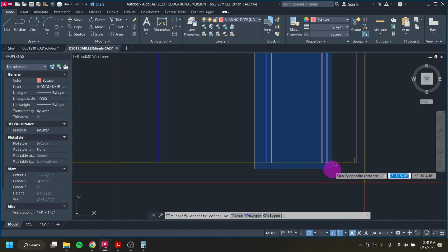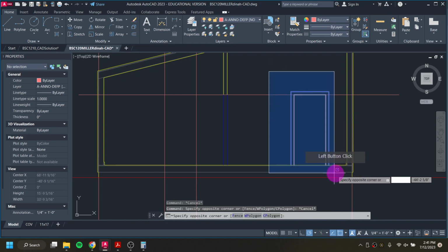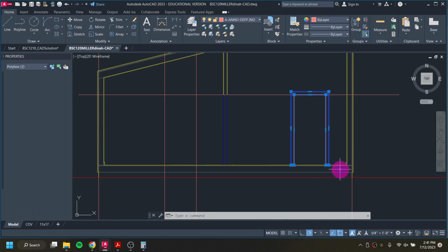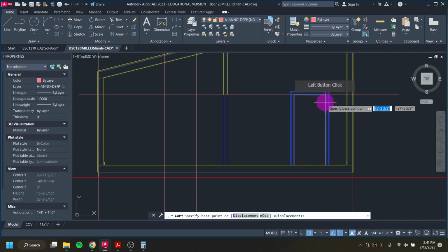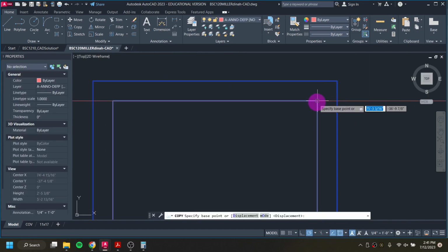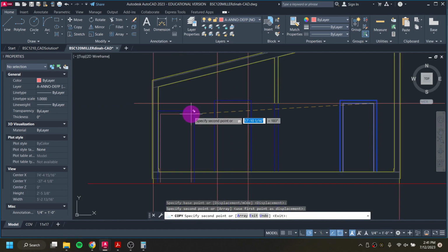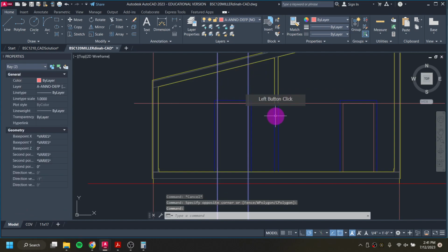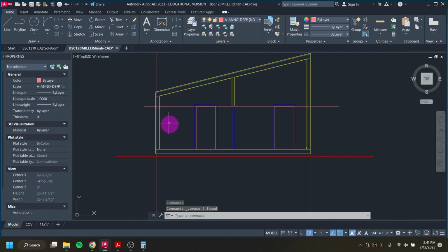And then I could take the doorway that I already have built out the majority of here and look to how I'm going from left to right with that, so I get a cross selection instead of a window selection. So I'm only picking up the door. I'll do a right click copy. I'll grab it by this top corner of the rough opening and I'll put it on that top corner. And then I can click on these rays after I hit escape and I can delete it altogether.